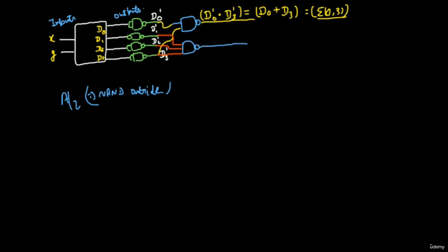Okay, I missed one thing. Don't get confused in that. These are going to be complements either. Either you can show it like this, or you can put the bar over on this. This is pretty much the same. I'm just putting the complement over here. Because the not part is here, we have to focus that wherever is the not part, this dot part is representing the AND formula, which is the logical multiplication. But because of this not part, we also need to complement our answer. That's why we reached this result.